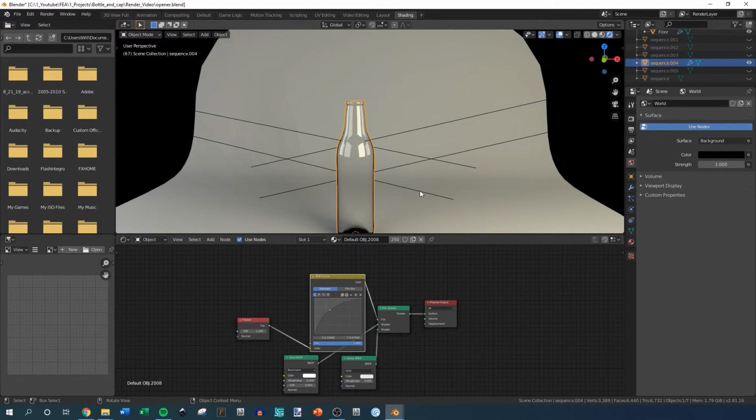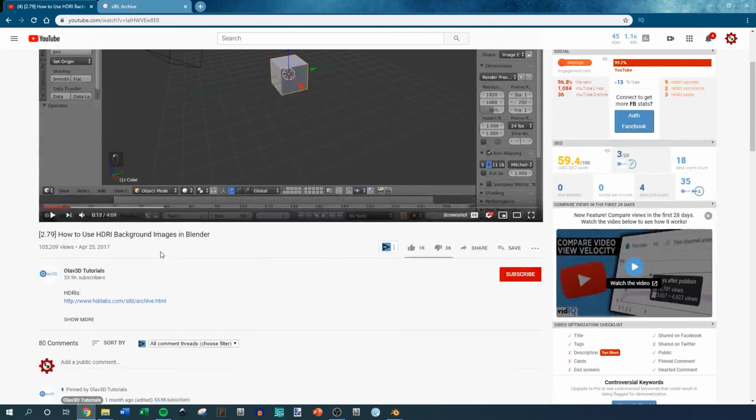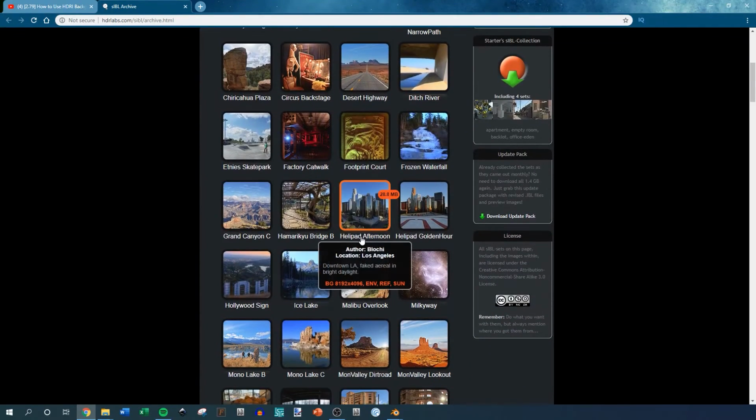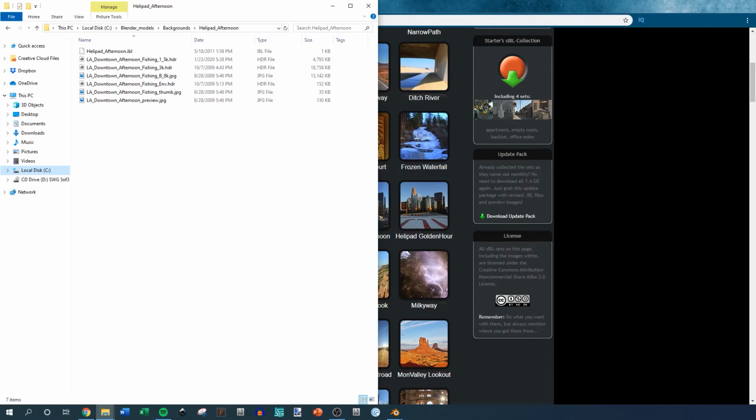Now you're going to need a certain type of file, and there's this video here, and I'll link this, that shows you how to do this, and also shows you where to download some of these free environments. The one that I used was this one called Helipad Afternoon. You just download it, and it's going to give you a series of files. You can use these HDR files, which are basically like a circular image or a cylindrical image that goes around in a three-dimensional way, and that allows it to reflect the different colors in it.